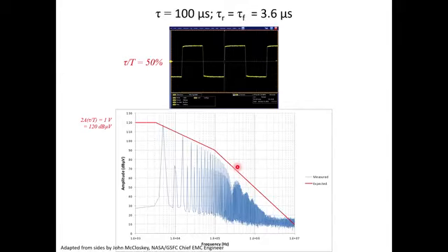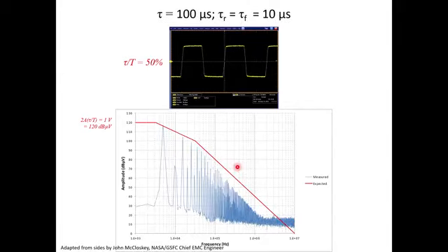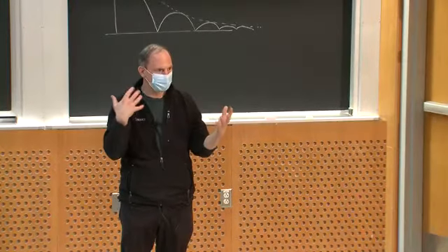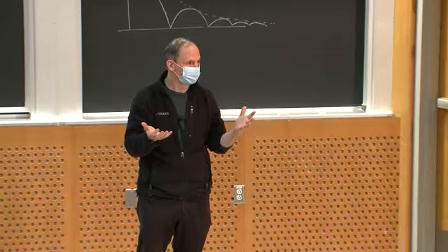If I make it 10% rise time, I'm really killing off high frequencies. Now, maybe in reality I wouldn't let my transitions take that long, or maybe I would. If you looked at the transitions in some of those waveforms we showed you in the last class, they were pretty slow compared to the switching period, right? Because you're using it to get the ZVS, all right?